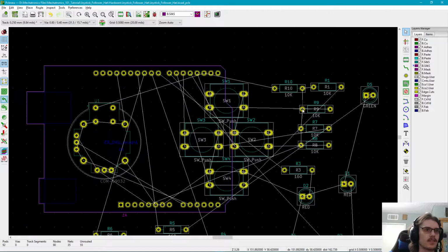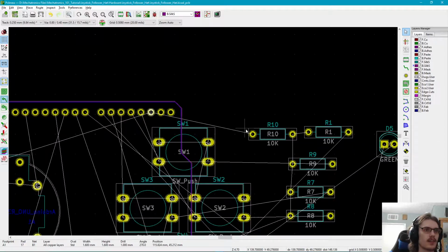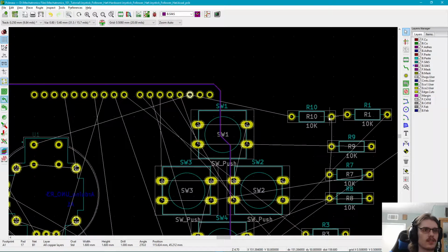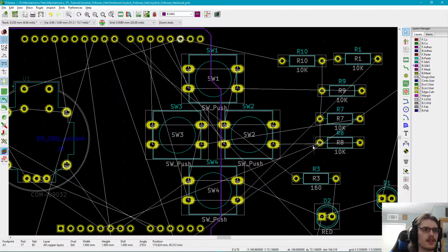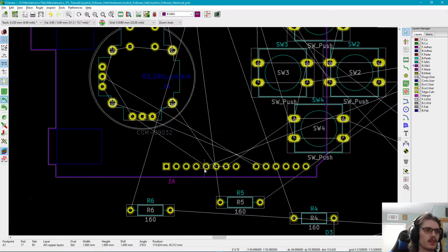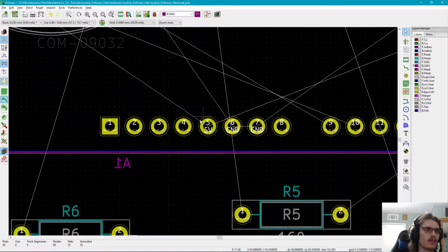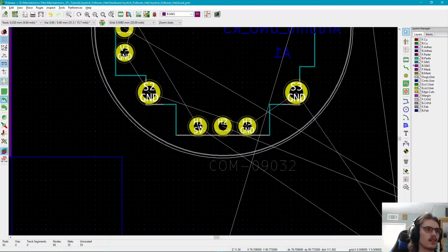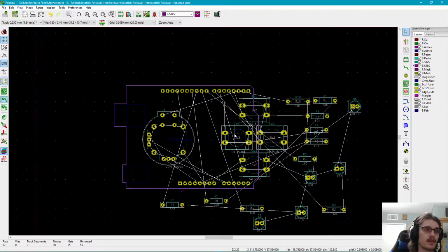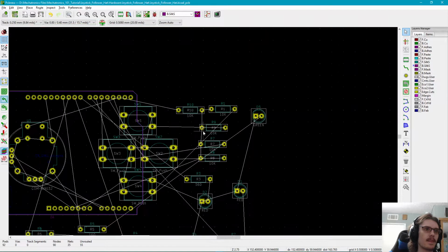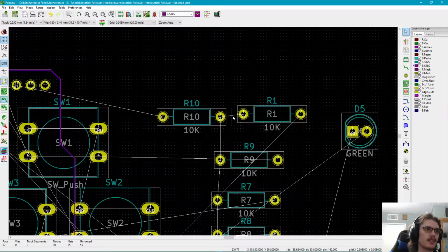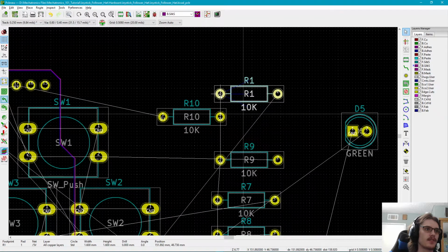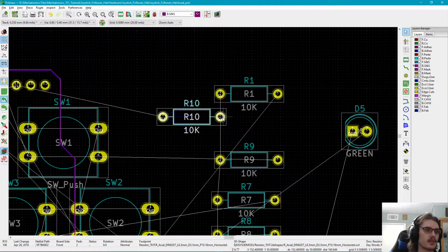How about that? So the 5 volts, they all seem to connect to, if we follow it, it seems like they connect to here. So we're going to need to figure out a way for them all to connect to here or to connect to here. It just needs to connect to some 5-volt pin in general. Because there's so many of them, what I'm actually going to do is wait to assign them to a spot because they're kind of flexible a little bit.